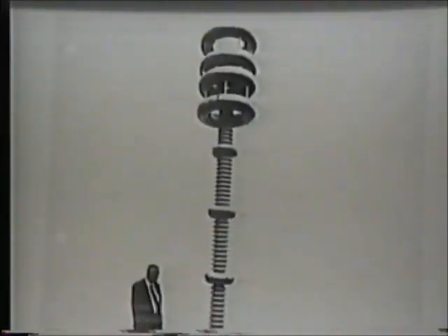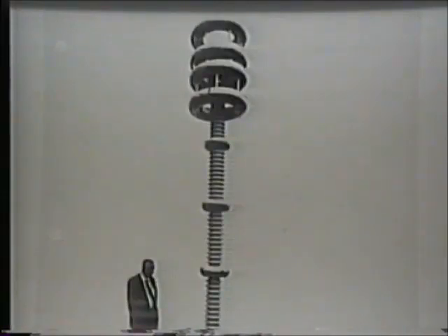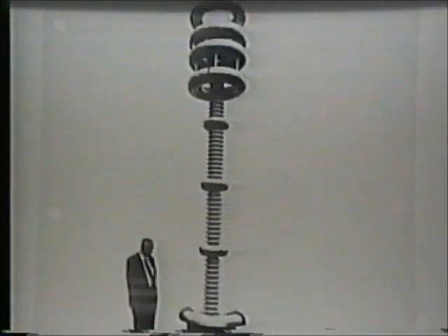Okay, in conventional measurement of electricity or high voltage, you have to use voltage dividers in order to get your instruments to work for you. As the voltage gets higher, these voltage dividers get quite large, and in this case, in order to use conventional measuring instruments, this thing is more than 9 feet tall, and it's good for less than 1 million volts. So you can measure up to 1 million volts with your regular measuring devices by using this divider to bring it down to where your instruments can work with it.